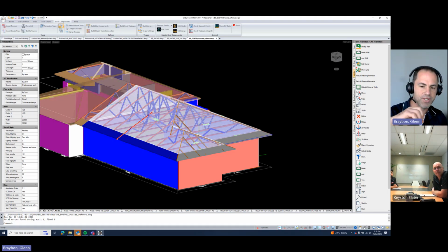And we want to develop the light gauge steel sections that we have into larger beam sections that we can use for the alfresco, whether that's a boxed stud on top and a box stud on the bottom, and then a web truss in between, almost like a flush double truss that would work as an alfresco beam.